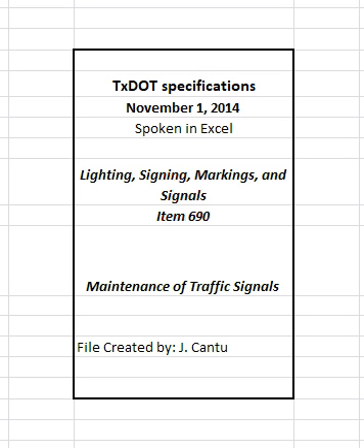Submit a materials list to the engineer for all poles, mast arms, and controllers needed. Pick up materials at the locations and times shown on the plans. Designate in writing the persons authorized to pick up the materials. Assume responsibility for all materials furnished by the department. Use materials furnished by the department for this contract only.